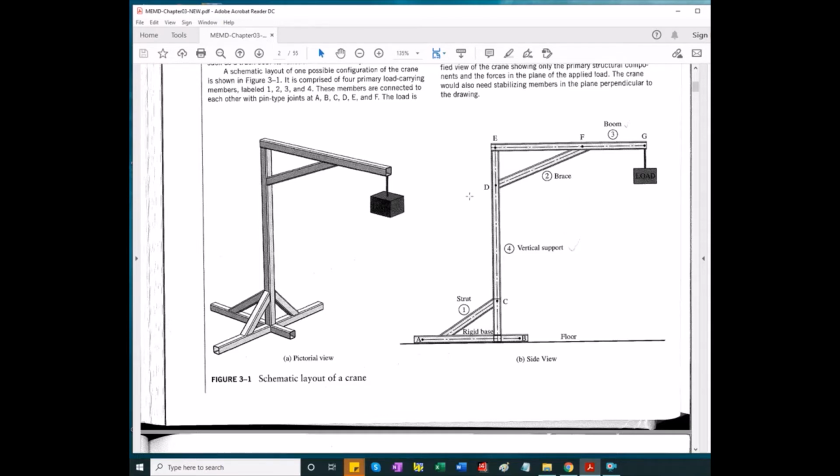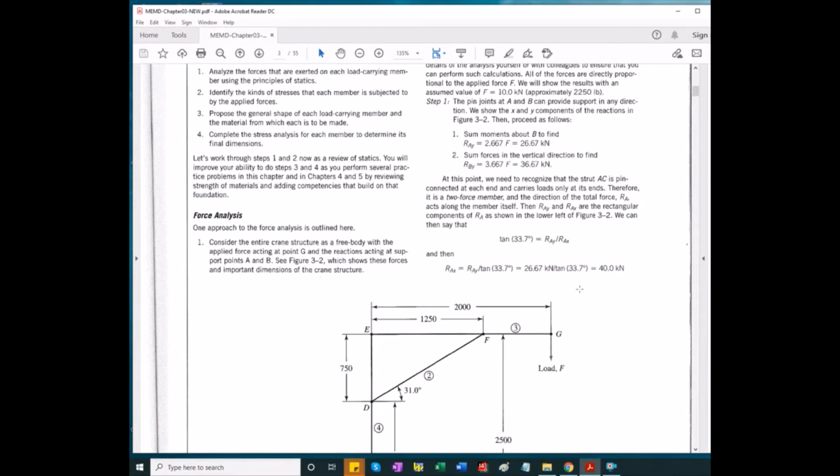It means that the reaction forces are aligned with the line FD and C, and a point that's not labeled here. We assume that they are pinned rather than welded, although we'd expect these to be welded, but in order to have the individual elements be statically determinate, we are assuming them to be pinned together.